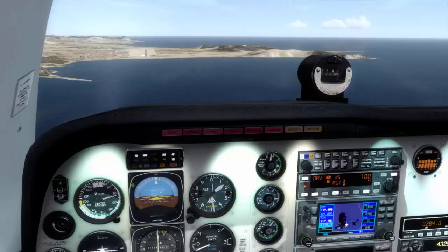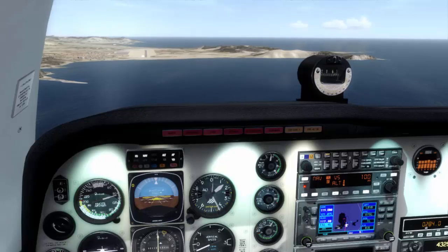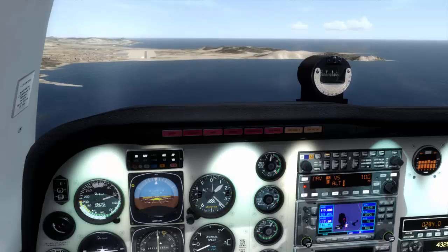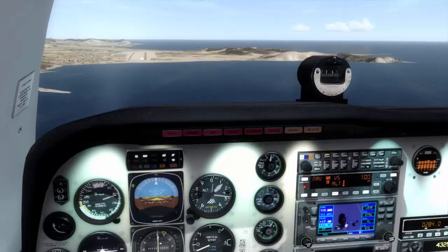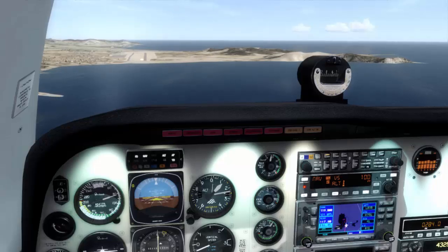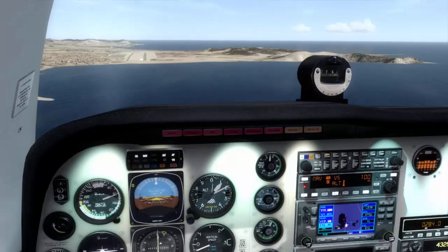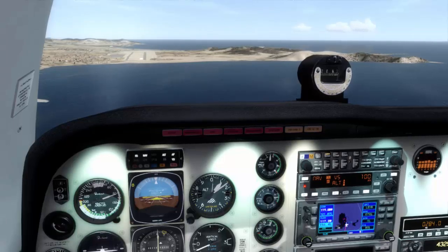And remember, the VOR is aligning our aircraft to a certain radial of the VOR that is crossing the runway, okay? So consequently we are also aligning our aircraft with the runway, but a VOR DME approach is not taking care of how the aircraft descends. So you have to program that in the autopilot, retrieving that information from the charts. For that reason, it's very important that you have the charts, because if you don't have the charts, you cannot proceed with the VOR DME approach, okay?